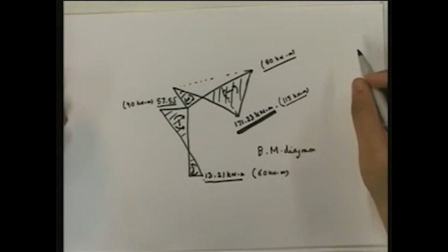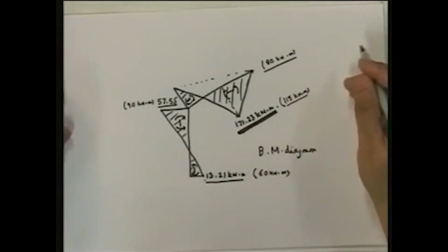In other words, now the member BC, up till now we were seeing, make it flexible. It's going to get much, much better as long as you do not have a serviceability limit. In other words, the rotation and displacement can be anything that it wishes to be. Then we thought that introducing flexibility was wonderful because it was reducing all kinds of bending moments in the structure. But you have a problem.